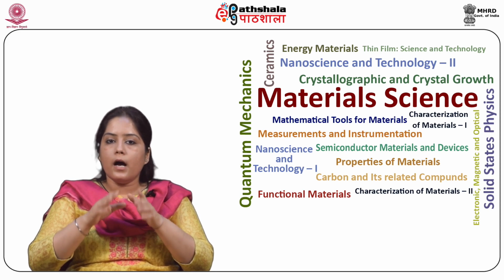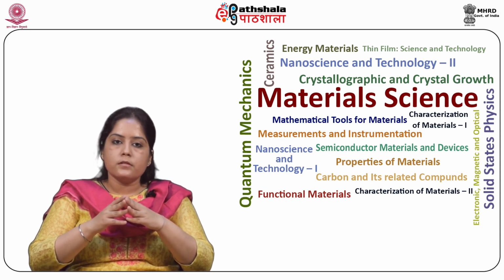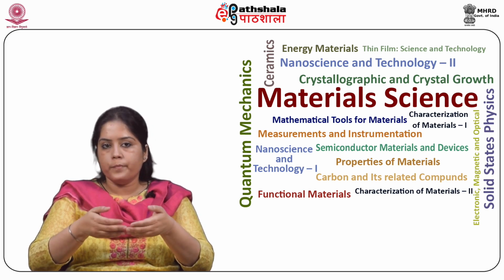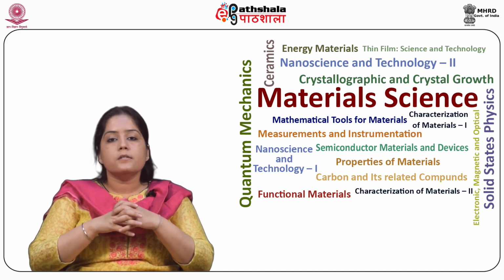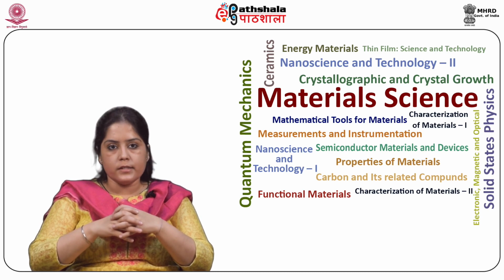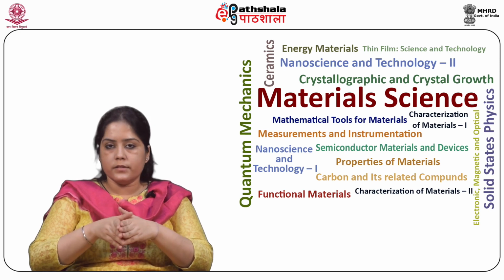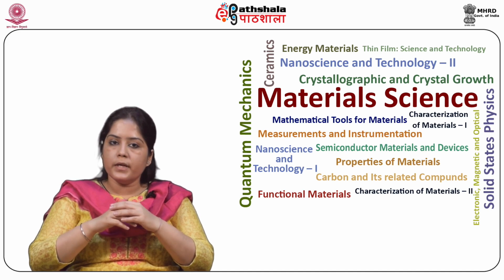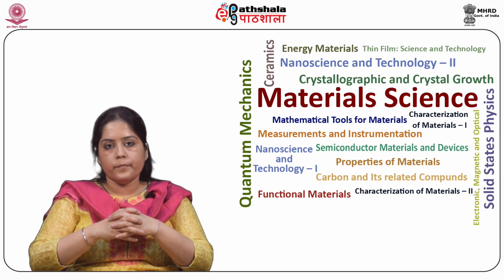Since the ion conductivity of such a polyelectrolyte determines partly the resistance and the voltage drop inside the electrochemical cell, a suitable polyelectrolyte needs to have a sufficient ion conductivity in order to achieve a good performing and efficient redox flow battery.